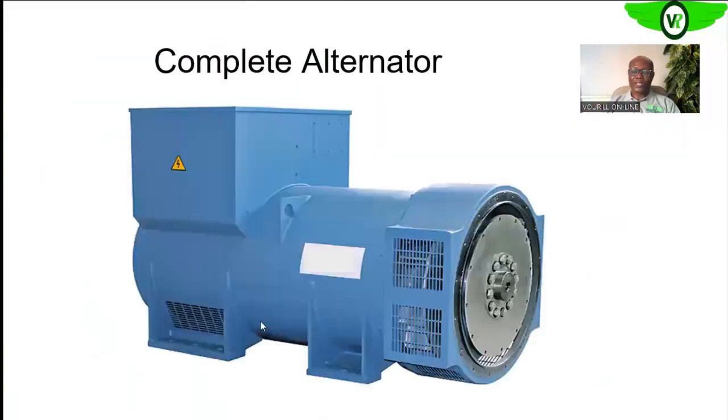So here we can see a coupled alternator. So we have the field winding, this is a complete alternator, okay? So this is the part, this plate is what is coupled to the flywheel if it is a diesel-driven engine, okay? Or a gas-driven engine, or the steam turbine, or what have you. So if it's a steam turbine, here is coupled to the shaft that comes out of your gearbox. If it's a gas turbine, the same thing.